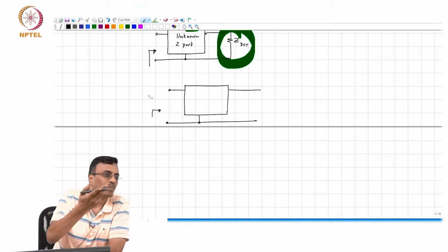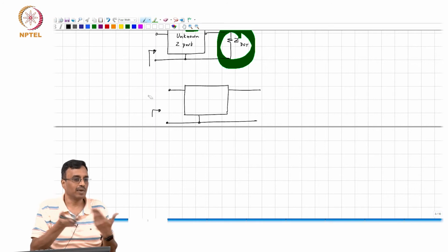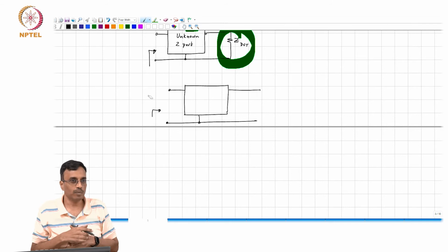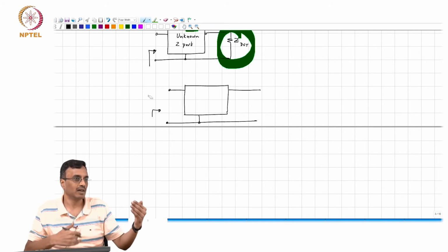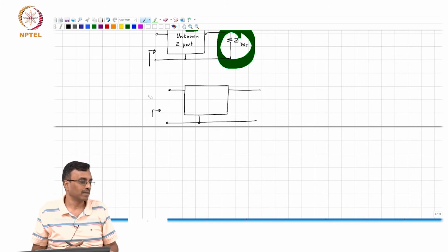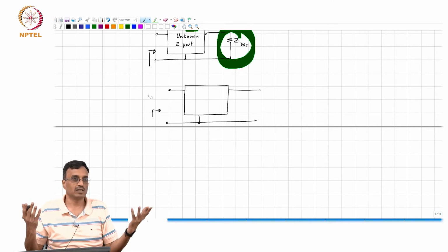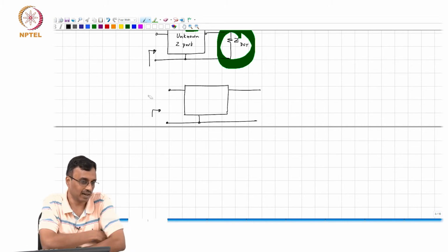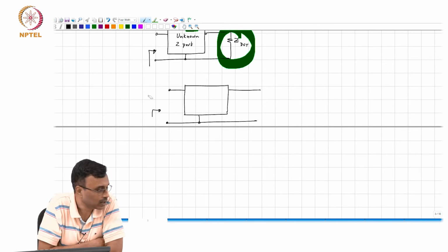Measurement precision is a problem, right? When you try to invert those matrices, if you use 50 ohms, 50.1 ohms and 50.2 ohms, the equations become ill-conditioned, because you pretty much have the same equation. Just copying the equation 3 times doesn't help, because the rank of that matrix is basically still close to 1.